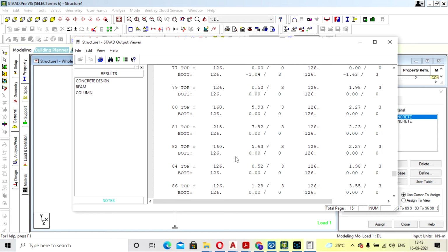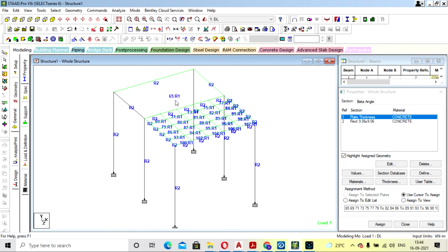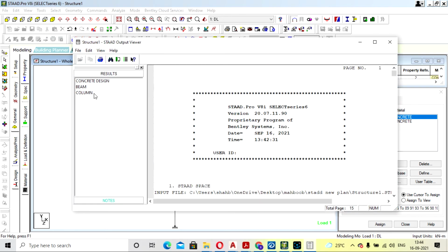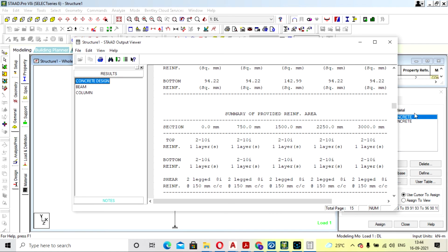Okay, so the steel will be increased, so more strength will be provided to the slab. Okay, so nearby the center the value has been increased, and here only 126, so the value will be distributed to whole parts. Okay, so more, or accurate, steel will be provided over there, but it was so confusing that nobody designed the slab from Staad. That's why.